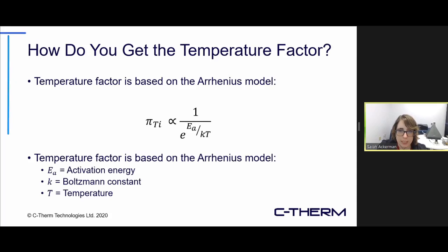He contributed many things to the field of thermal analysis and kinetic rate analysis, one of the key ones being this concept of a rate constant or a rate law, where the rate of an event, in this case a failure rate, is proportional to an activation energy, in this case of the device or the component that you're looking at, divided by the Boltzmann constant multiplied by the temperature.